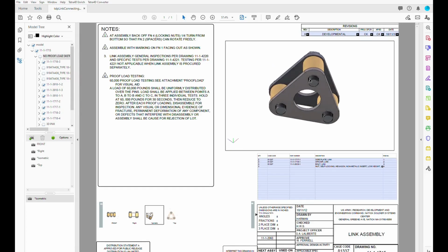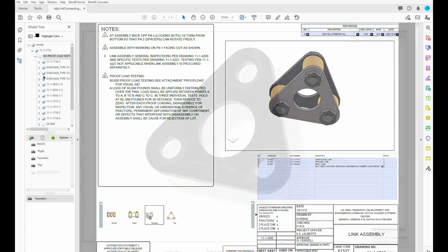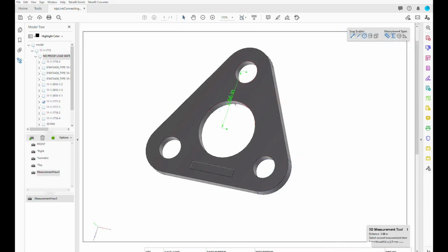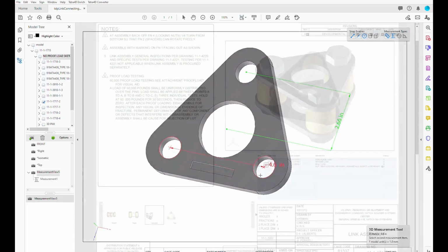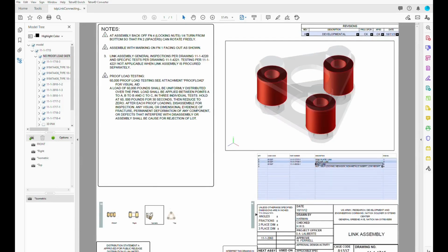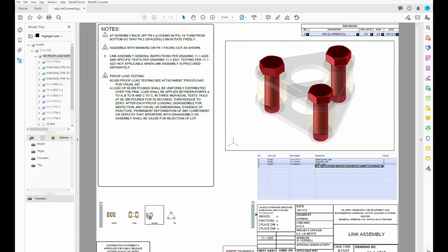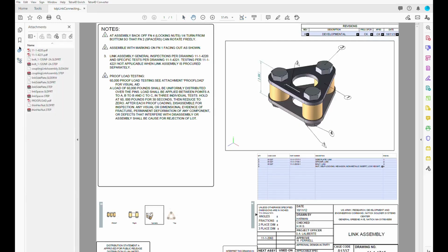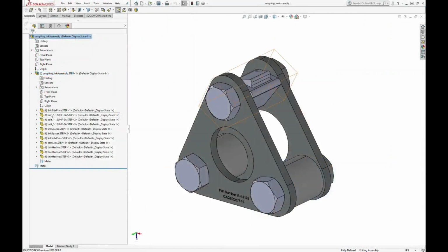The 3D views provide the reader with the ability to gain greater insight into the product by taking measurements and changing the perspective in real time. Associativity between the geometry and the non-graphical attributes also enables the display of information about the part through a graphical selection. But the greatest benefit of the 3D technical data package are the attached 3D data files that are used to support machine-to-machine communications.